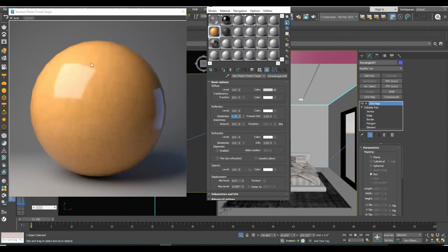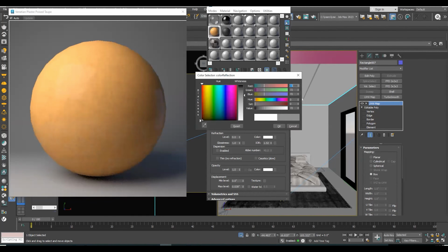As you can see here, your reflection value is more blended and more blurred. So if I put 0.4, then your reflection will be more blended. Okay, so glossy works with the reflection values. If you ask me what is more standard, I would say 0.85 for a better blended glossy with this reflection. Okay, and you need reflection point like this for a wall, not much more, just like this for semi-gloss material.